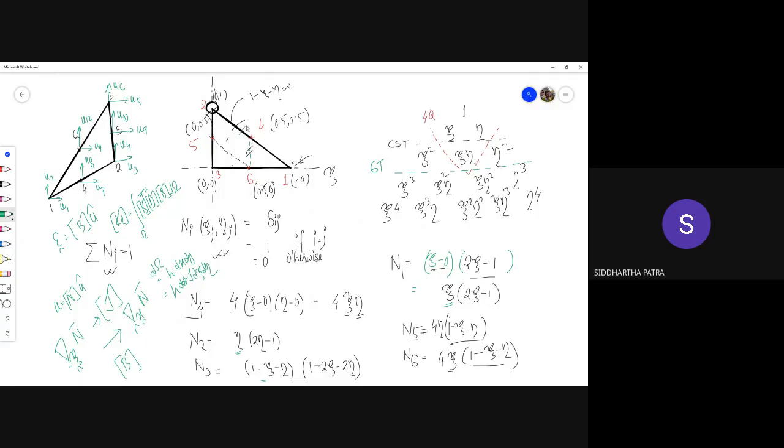On the third side, neither xi nor eta is zero, but they must satisfy 1 minus xi minus eta equals zero. So one constraint is there, and if you integrate, in each case you get the identical expression for the force vector, because the shape functions on that line are linear.